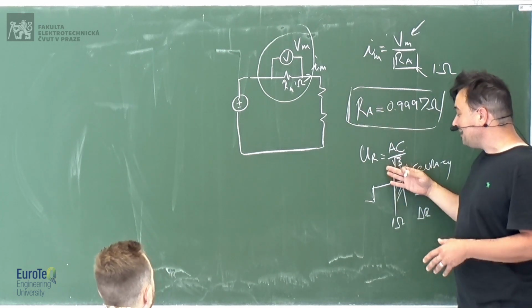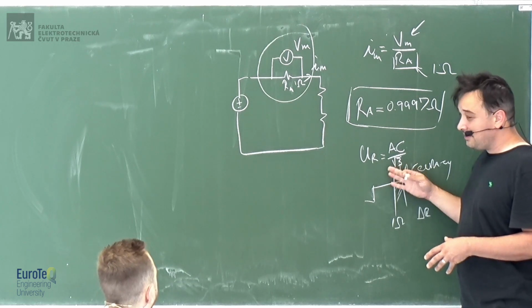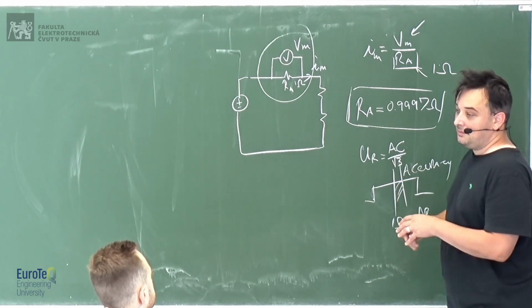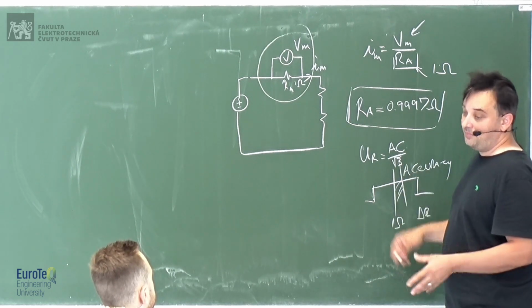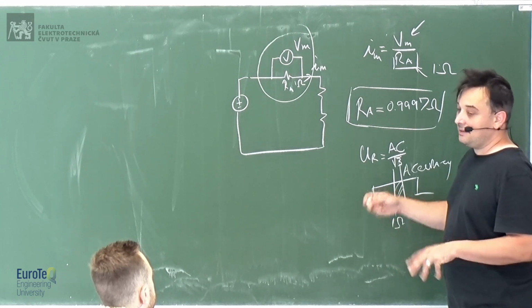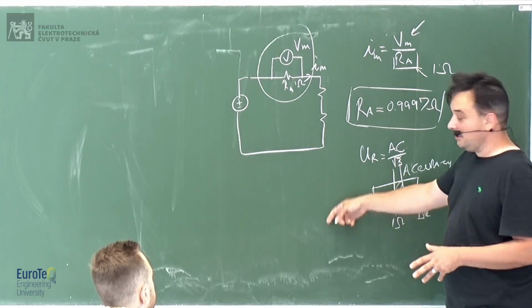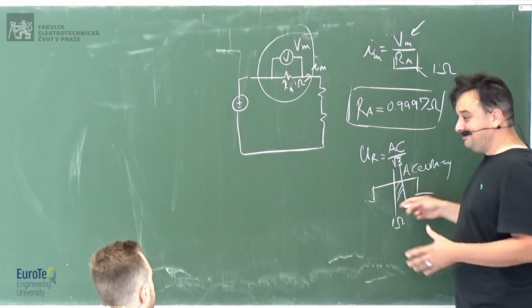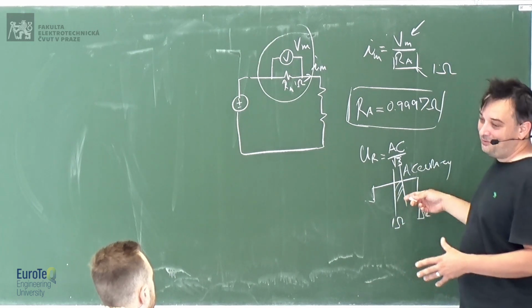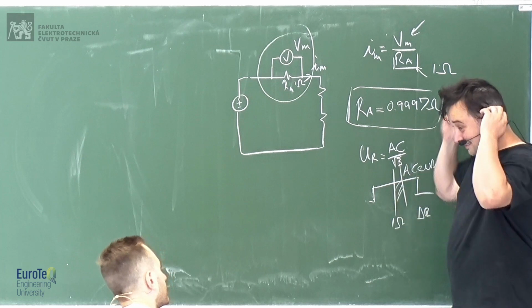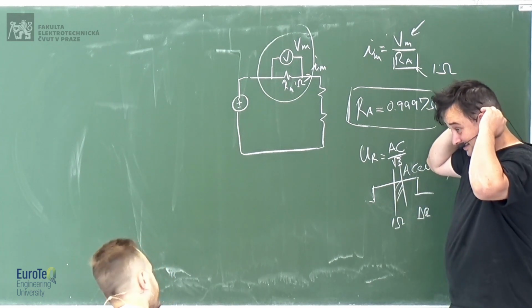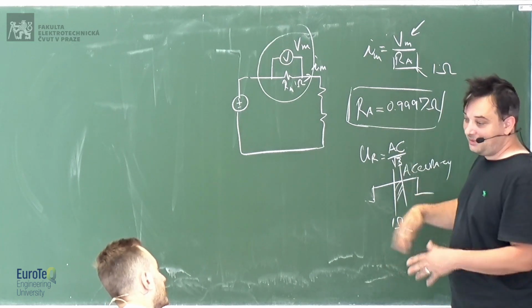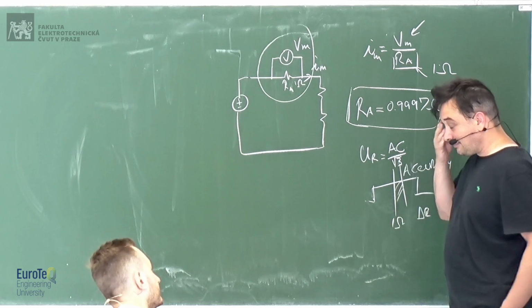Again, in this case you might have some statistical distribution, because if the manufacturer sells you one resistance out of the batch, before selling it they made some testing, and in the datasheet they give you some distribution of the test. I really don't believe it will ever be uniform, because they can use that distribution to divide the components up. Exactly. Then they will reject some bad ones, and they can put the other ones in a higher class.